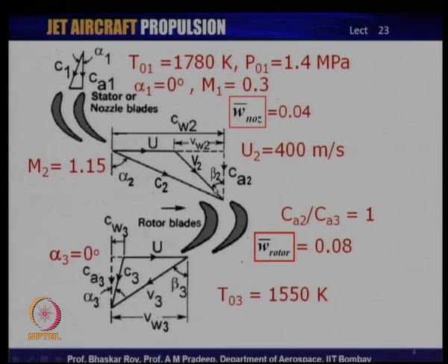And as I may have mentioned earlier, this is done deliberately, that most of the modern turbines today still admit flow into the rotor which is subsonic. It is indeed possible to admit flow into the rotor which is supersonic. That means, you can indeed have supersonic rotors, but normally in aircraft gas turbines even today it is not a done thing. Supersonic rotors have been used in other applications, notably in turbomachinery applications in spacecraft, but they are normally not used in aircraft gas turbines.